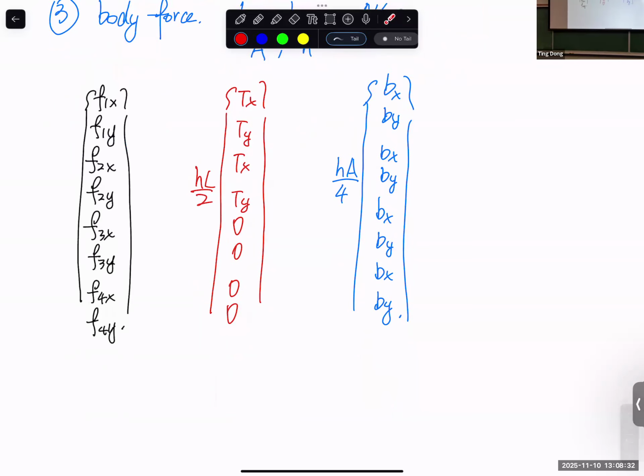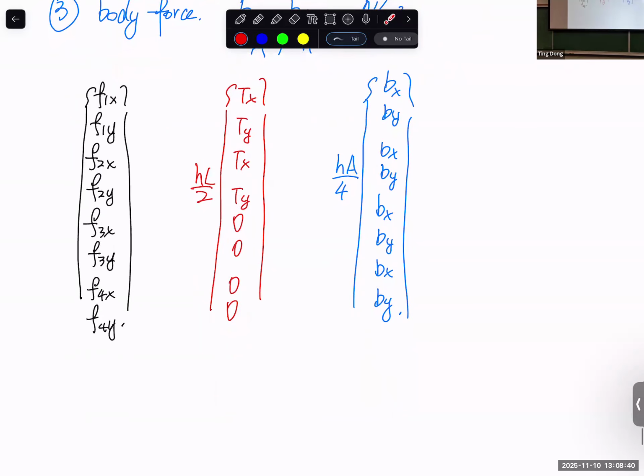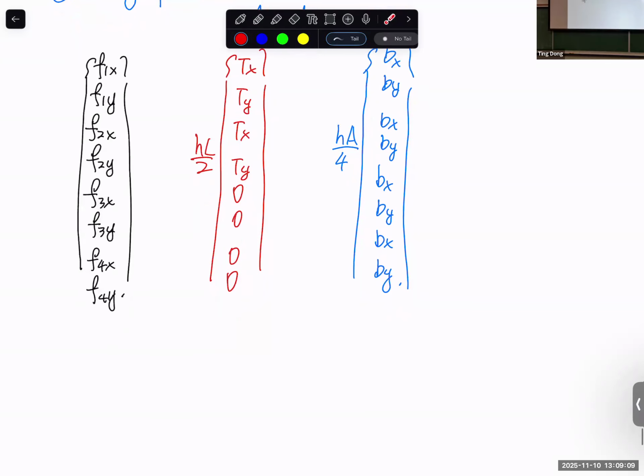It's still going to be equal to a matrix times your Q vector, right? Whatever we're doing, even in this version still. Yes, FEA is about KQ equal to F. I want to make sure that stuff got changed. Nothing changed. So the whole FEA is always about K stiffness matrix times Q node degrees of freedom equal to force applied. It's the same as bar element, 2D truss, beam element, CST, LST, or whatever element type you will use in FEA. It's always KQ equal to F. Any other question?